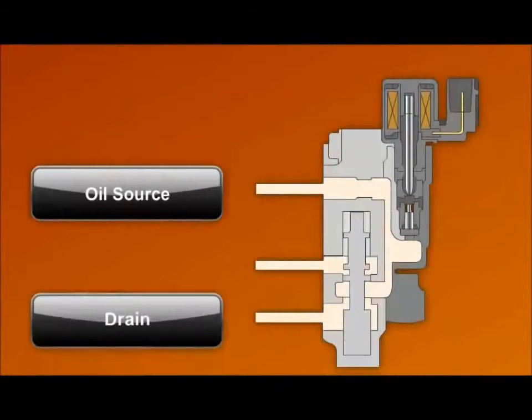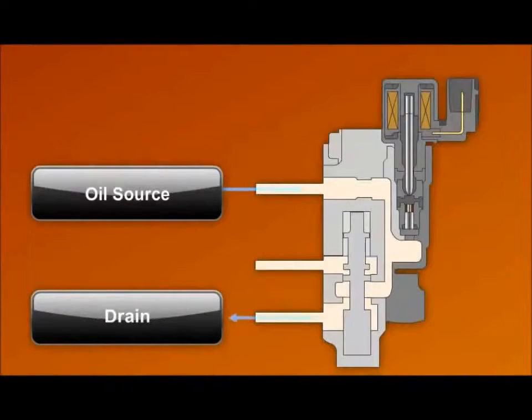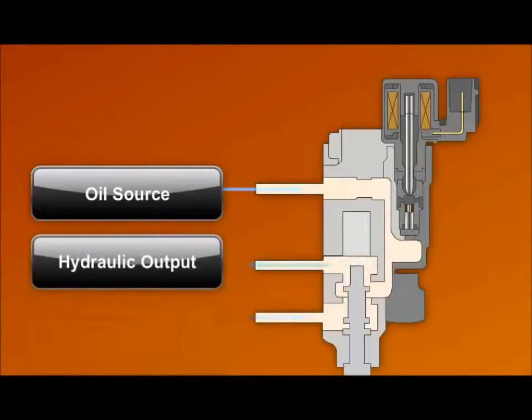The final system component is in the cylinder head, where oil passages feed oil to cam-control solenoids. When energized, these solenoids hydraulically operate VTEC pistons or a VTC actuator.